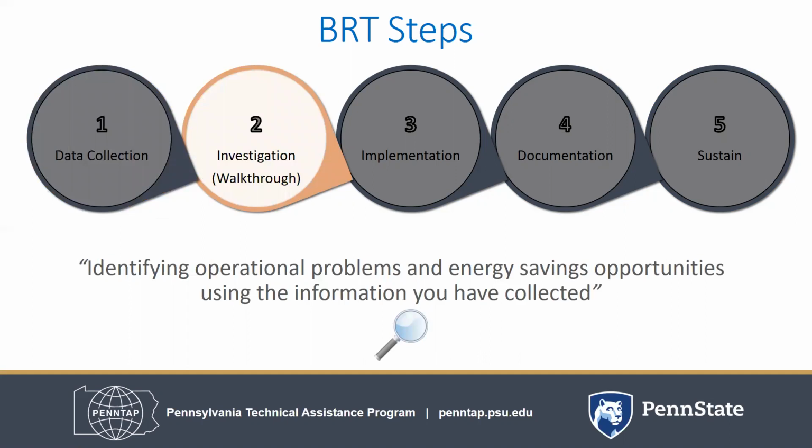Once you have the data collected, now it's time to investigate. Look at your building's conditions and operations. You want to investigate both during the heating season and the cooling season to see if everything is operating properly. You want to log all information and observations during the walkthrough. This will help you capture opportunities and ultimately calculate potential energy savings.